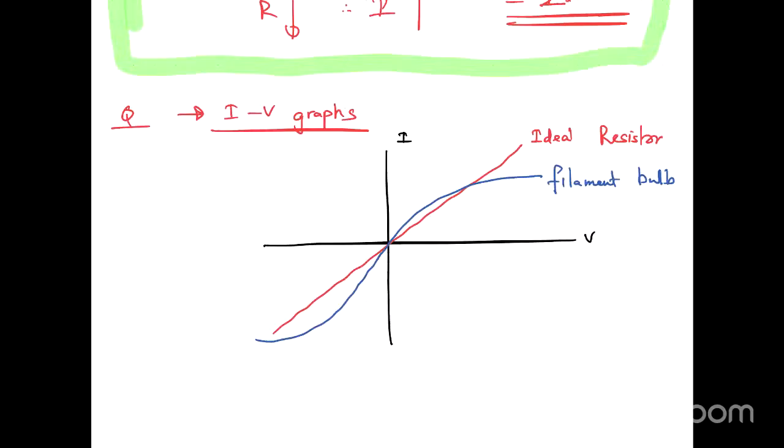Normally, the reasons for these shapes are not actually mentioned in this syllabus, but in your A-level syllabus, it is mentioned. So here you will have a minus value like this, and at a 0.6 voltage value, you will have this sort of increase. Just remember this value can change depending on the material that we are using to construct the diode.